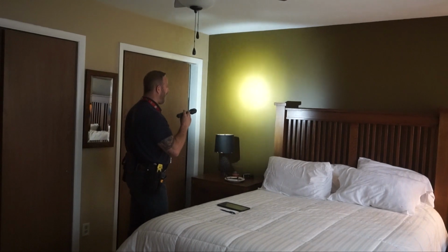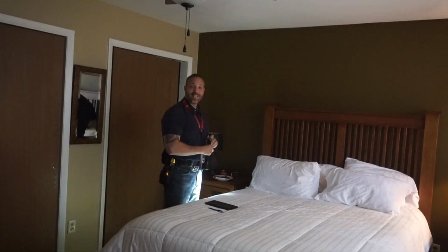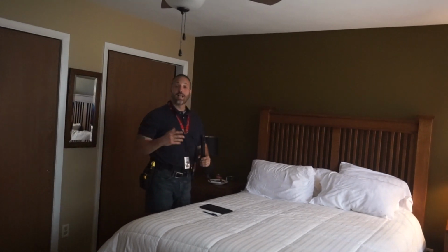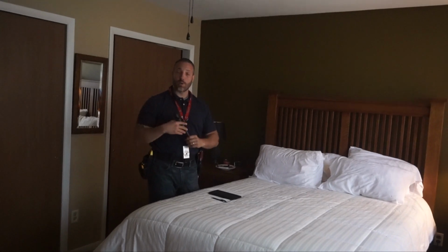Once we do that, again, we're going to look at each of the walls. You're looking for cracks. And if there are cracks, are there any ceiling cracks? Are they continuous to the floor itself? Again, if they're cosmetic, it'll be at the joint between the sheetrock.